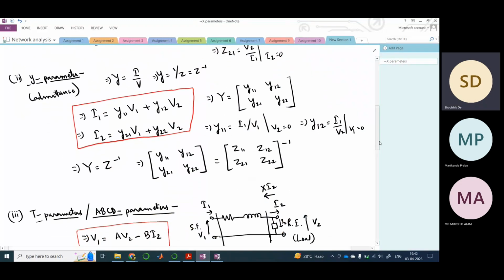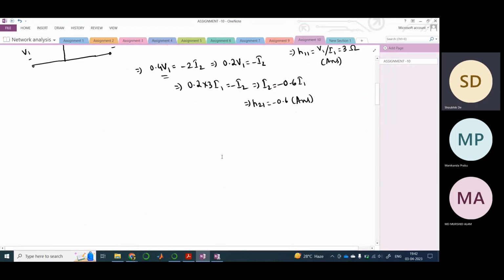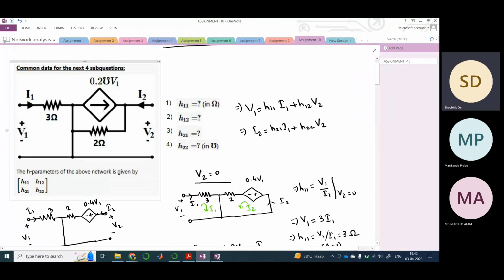See, this analysis is more simple because you just have one equation here, and in the other you need to write this first, then do this, and then you see that V2. I mean, this will do, but this will take more time. So my suggestion is, when you see a current source and a resistance which is connected to ground, so this whole part is grounded, right, because this is shorted.